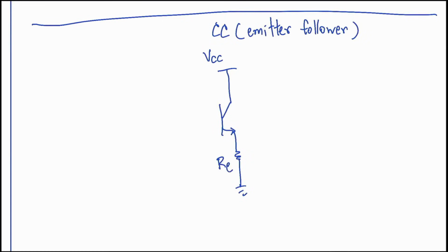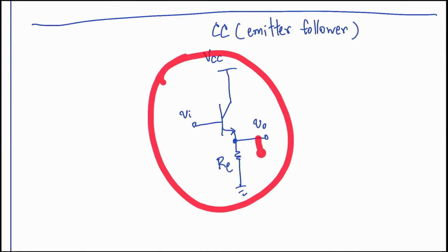Finally, for this configuration, the input signal enters the circuit directly at the base pin, which is a key characteristic of how this amplifier operates. So this right here will be the V input, and this will be the V output at the emitter pin. And we also have the resistor R that we have been working with. This one is given as R, right? So if the bias circuit is like this, the R load will be connected in parallel with the RE.